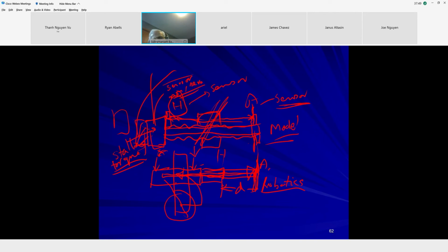Now, if I ask you, why would it be so difficult to control the intermediate position of an air cylinder? So, a simple model. I have an air cylinder that is pushing a load, and I am applying air pressure here or here. To retract, I apply here, it will retract. To advance, I apply air here. Why would it be difficult? Say it is capable of going up this far, but I want to make it stay right here.